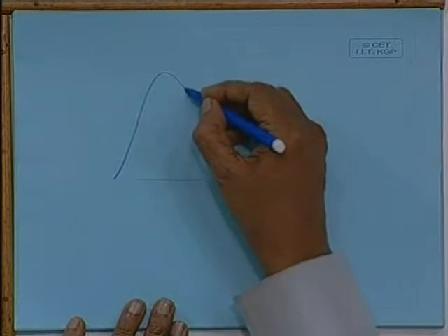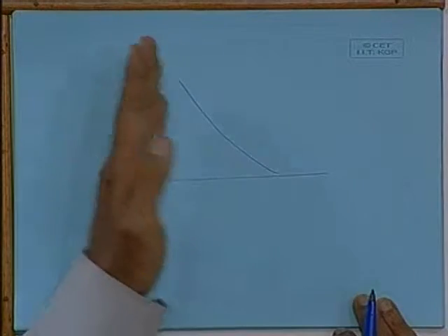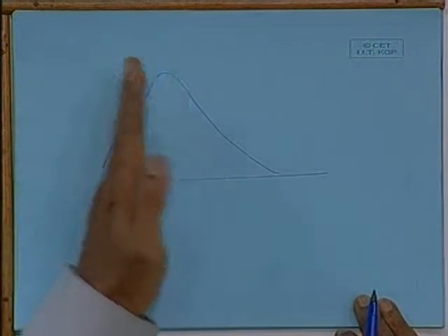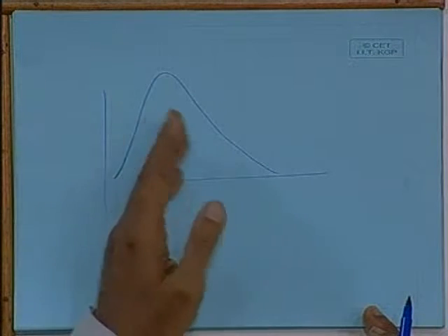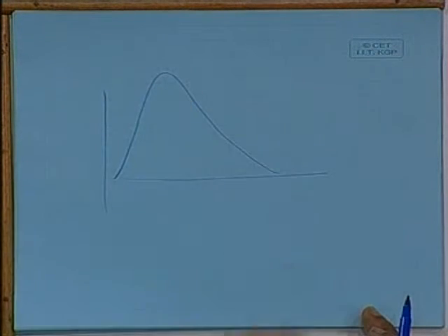Another interesting thing we found, that for the new ships, those less than 10 years, if you draw a probability density curve of thickness diminution, you will get something called a gamma distribution, like this. That means thickness reduction is maximum towards the left hand side, and large thickness reduction is small.